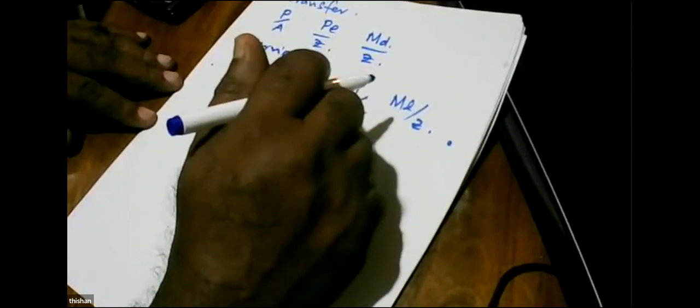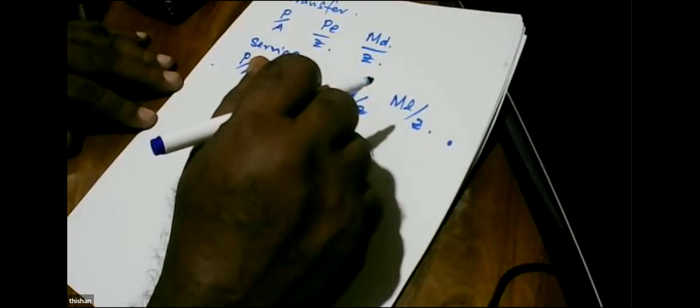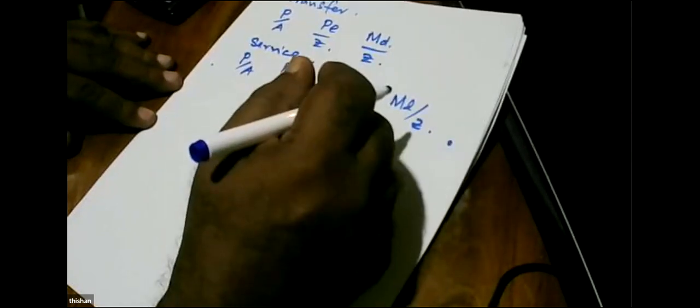So initially the beam is at the yard, no live load moment, only the dead self-weight. Now we have lifted the beam and kept it and finished the bridge. Now we get dead, and we can also get two deads. One is the dead that has applied as the self-weight, and then we can get another dead. So we'd say MD1 and MD2. We are getting an additional component of carpet that we place on the bridge, or some screed that we place on the beam. So whatever the dead loads that we are going to apply later.